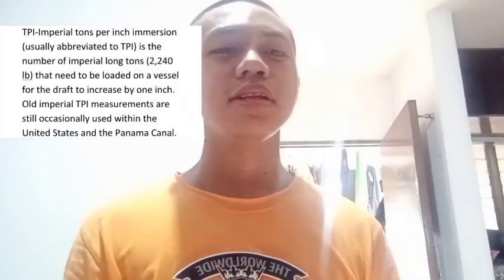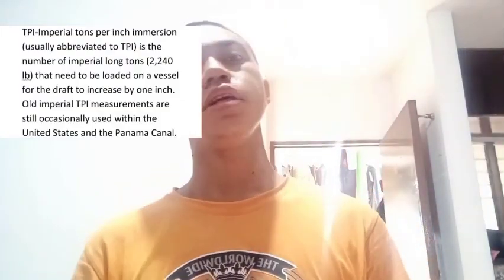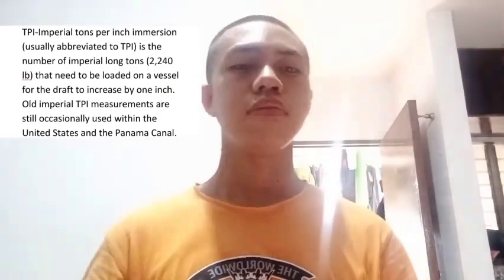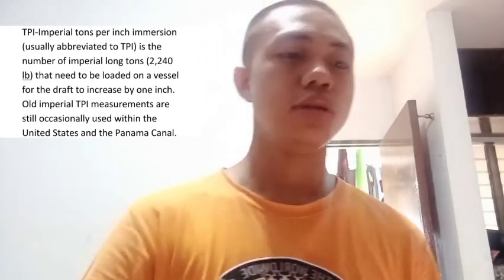Good afternoon. I am Rayan Isanyo and I am here to elaborate to you what is TPI, TPC, ITM, MTC or MCTC, mean forward and aft draft, and mean midship draft. TPI, or imperial tons per inch immersion, commonly abbreviated to TPI, is the number of imperial long tons, 2,240 pounds, that needs to be loaded on a vessel for the draft to increase by 1 inch. Old imperial TPI measurements are still occasionally used within the US and the Panama Canal.